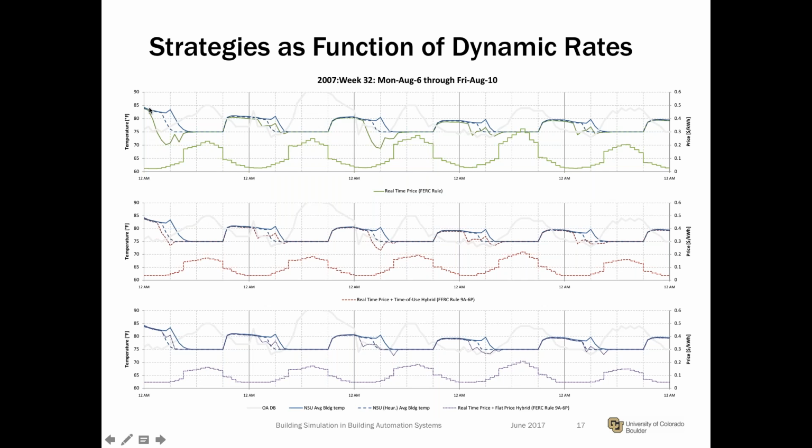One thing you can see is that from the temperature perspective shown on the y-axis, when the price incentives are strong, there is a significant amount of activation in the building on one day, but not necessarily the next, right? You can see this Monday, the building is pre-cooled significantly, not the next one. The third day, yes, again. So there is some magic to what the outcome of the optimization is, which isn't always easily predictable.